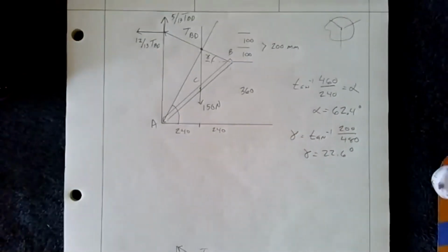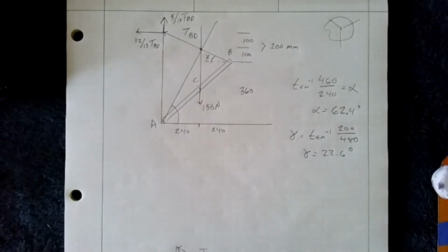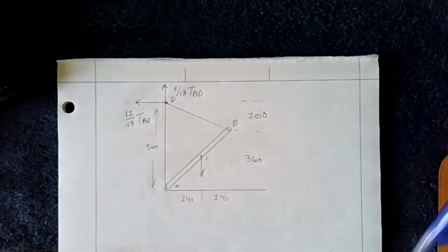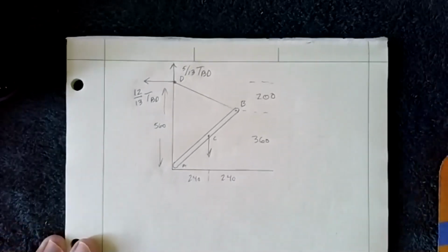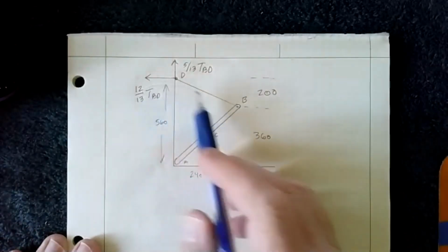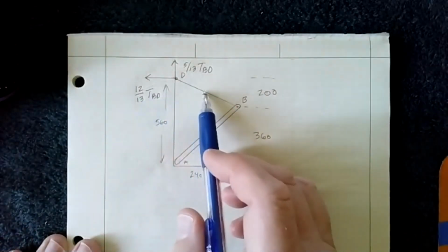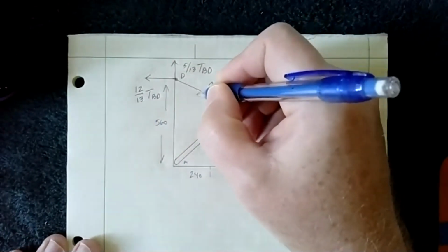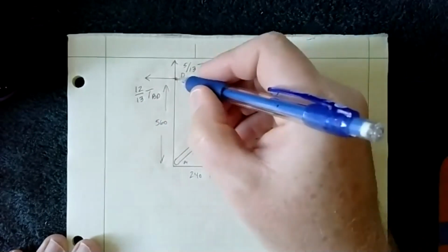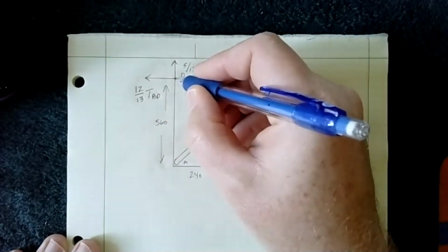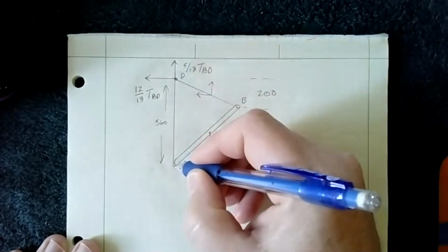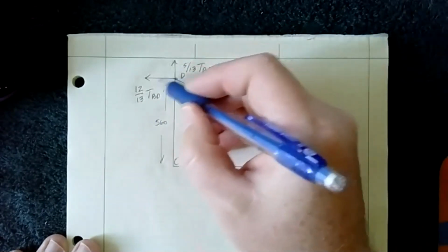So coming back up here, let me pause for a moment and redraw this. So there it is, drawn. Now, remember I said that these would be important up here. So what I've done is I've taken tension TBD, and you can break it up anywhere you want, really. You could break it up there, you could break it up there. But if I break it up and move it all the way to here, then this vertical component no longer has any contribution to the moment about A, and it's all just one.